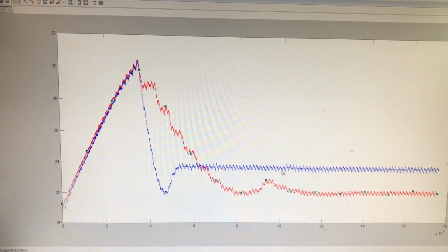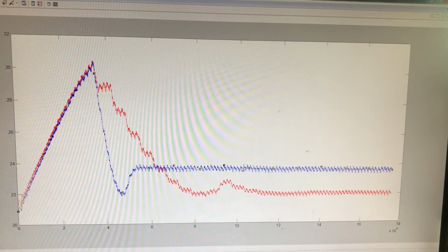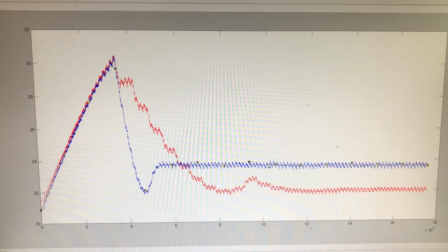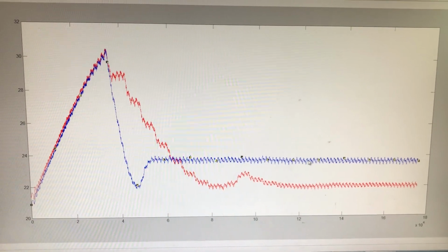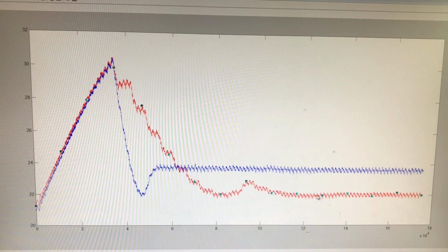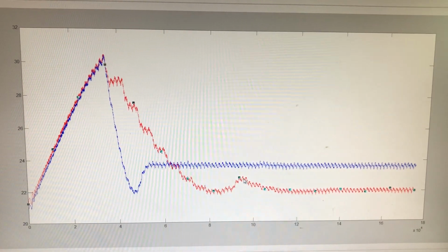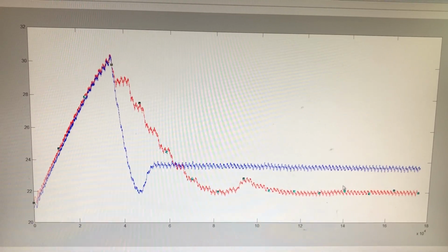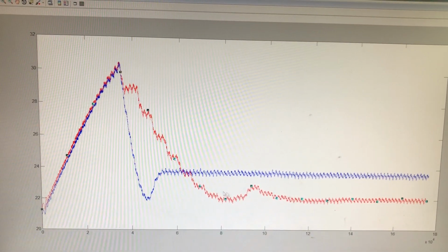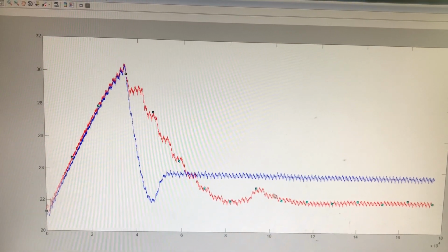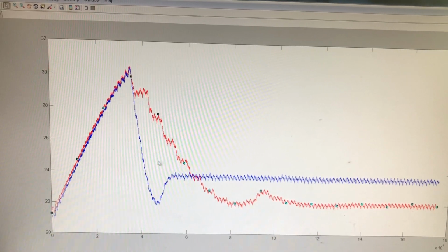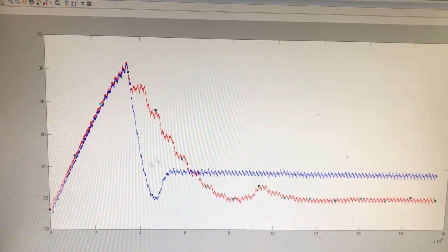Due to the parameter deviation, the model of our loss model control may not be accurate. So it will not converge at the minimum power point. However, the surge control does not depend on the accuracy of the model. It can achieve better convergence. However, the searching step is also long, and more power will be lost in the transient stage.